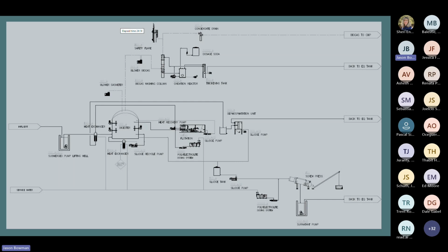We're talking about our specific anaerobic dissolved air flotation mechanism. It's typically polyelectrolyte only. Sometimes, depending on the exact feedstock, the exact waste that we're digesting, we may need to change the chemicals, but typically polyelectrolyte is all that is required. Sometimes ferric chloride is actually a good thing in these systems. They can help kind of maintain the H2S buildup within the reactor itself.